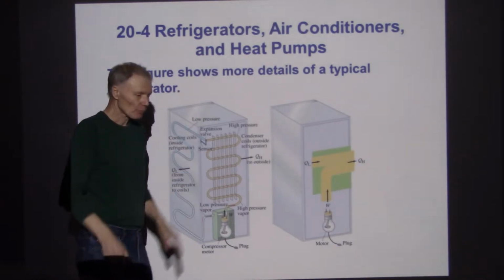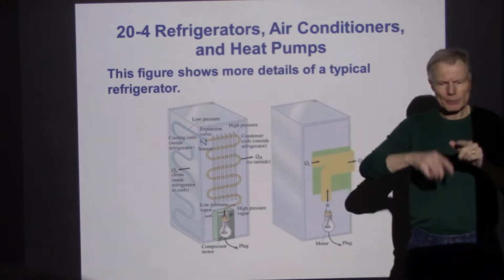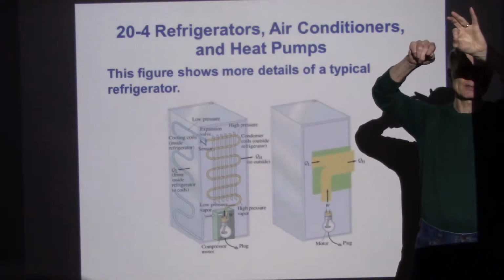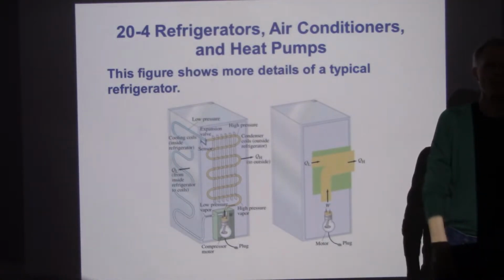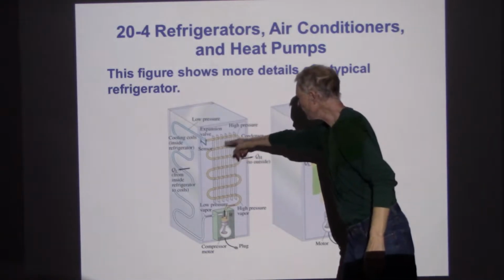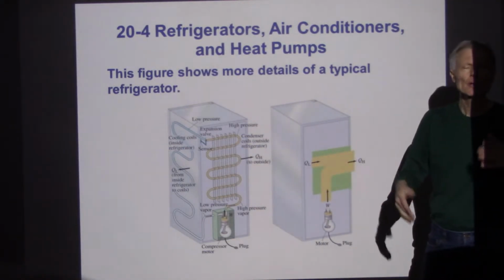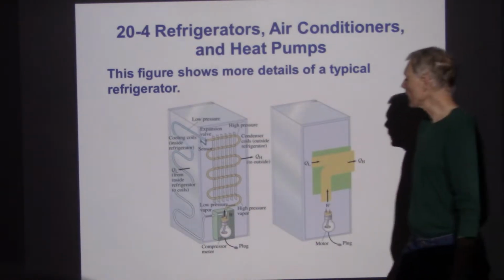So that's it. You build a compressor, you build a bunch of pipes, you run half the pipes up to where there's an expansion valve, and then the other half of the pipes. If you keep operating that compressor, this set of tubing is going to be at a high temperature. The other is going to end up at a very low temperature. What could I do with that?